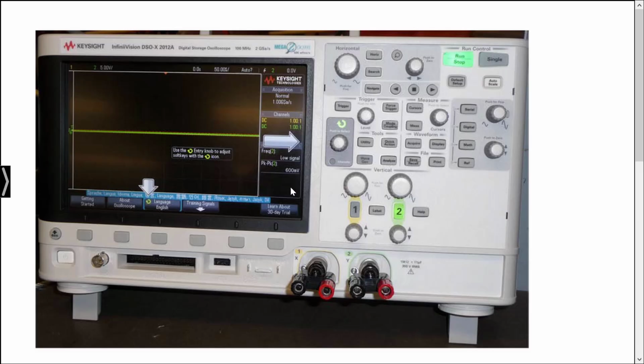And as you can see, with the oscilloscope, channel 1 and channel 2, they both have two inputs, a plus and a minus, which is a red is the plus and black is the minus. So this is where you will make your connections from the actual breadboard. So if you want to measure a waveform from the breadboard, you'll make connections from the breadboard to the oscilloscope.